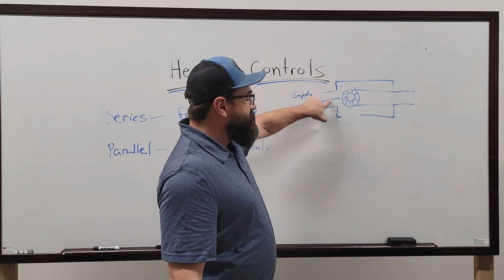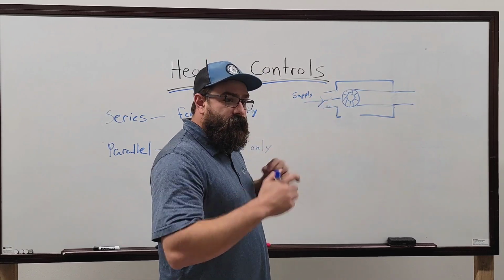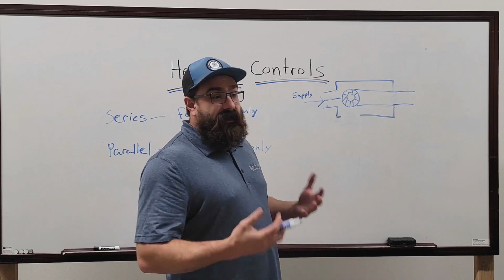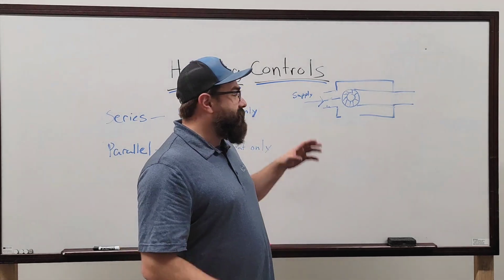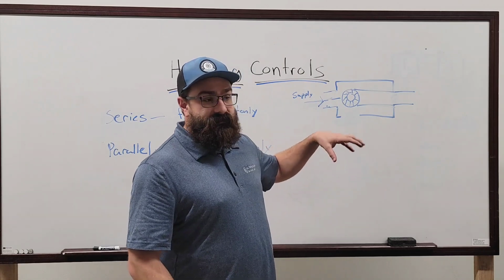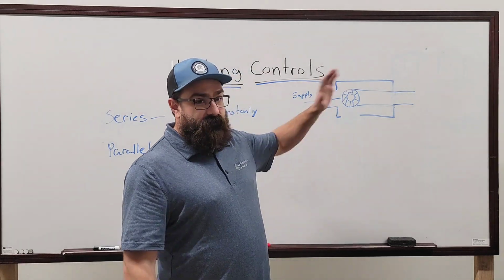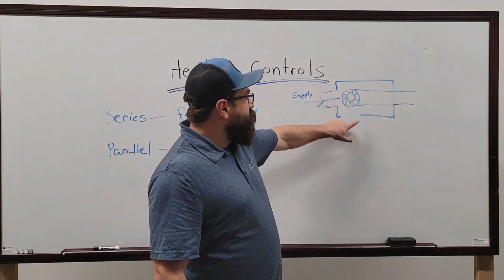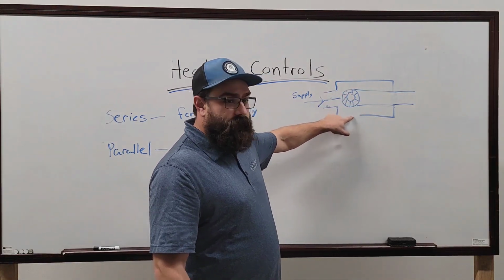We command this damper to its full flow value. Say you have a box that can physically do 2000 CFM, but it may only be designed to serve 1500 CFM. We would run it up to the full 1500 CFM, then they balance this fan to where they reach a neutral on this pocket.